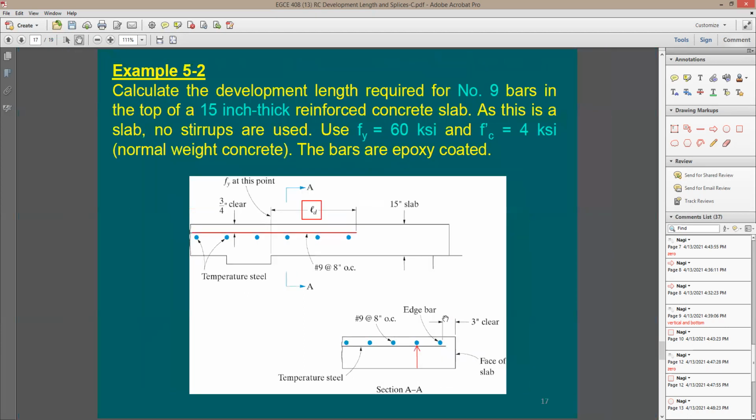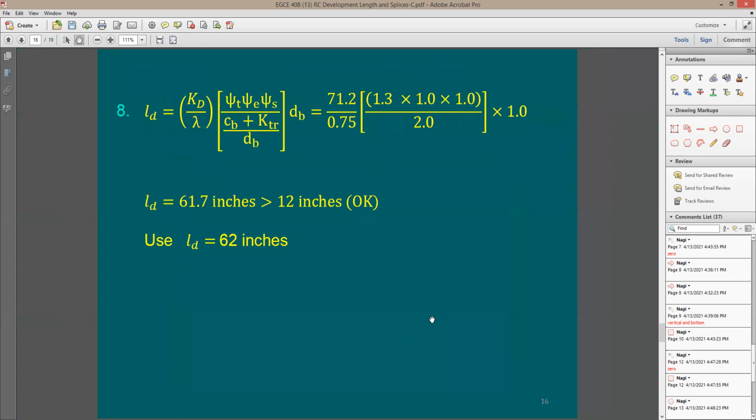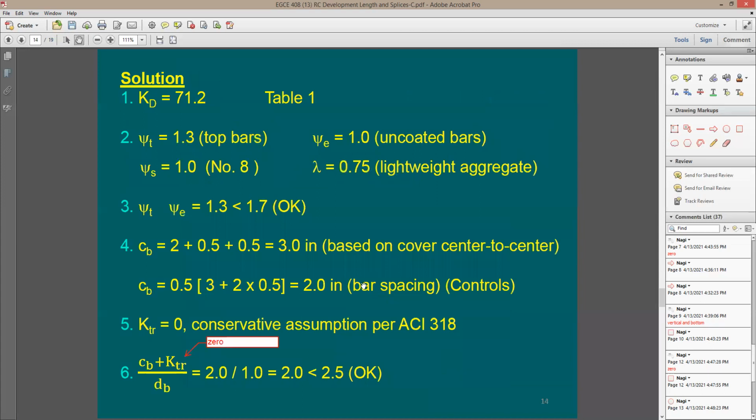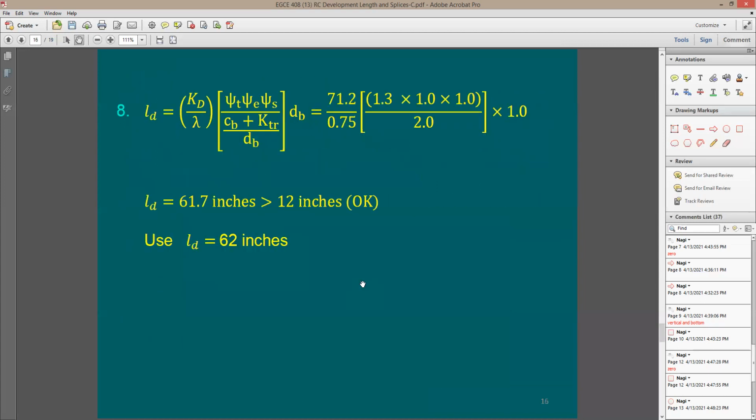I have a question here. The question is, do we really need to use here K sub ER, the reduction factor? I'm gonna say for this problem here, no one mentioned anything on what was needed originally. So if no one asked the question or gave me what is already needed, in this case, I don't really need to mention K sub ER. Just use it as is. I mean, use L_d as is. Don't reduce it.